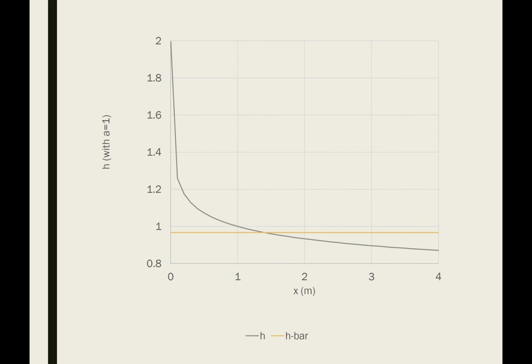So here's how those results would look plotted. If I were blowing air over a heated surface, at the beginning, based on that particular correlation, we would see a higher heat transfer coefficient, and then it would gradually decay and become lower. But if we wanted to look at the average, again, an average is just an average, so the average from 0 meters to 4 meters would look like that. However, if we wanted to take a different average from 0 to 10 meters, then because our local coefficient keeps on decaying the further out you go, gradually our average would also decay.